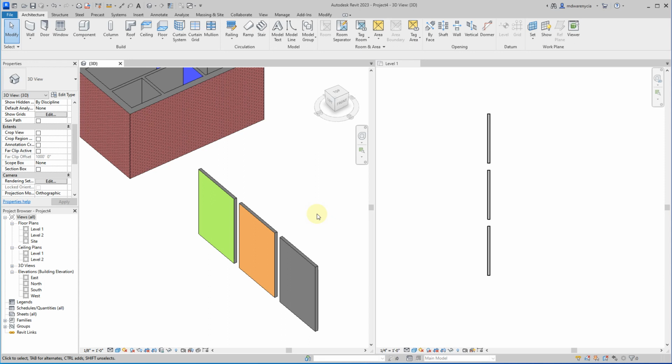So that's now two different wall types I'd need to have for that. And then another wall shared with another bedroom, which uses a different wall color. So now you need three wall types. And then another wall is shared with a bathroom, which is a fourth wall type. So you might need as many as 4 to 6 wall types sometimes if you have a really complex set of colors in your structure. So keep that in mind when you start setting things up.